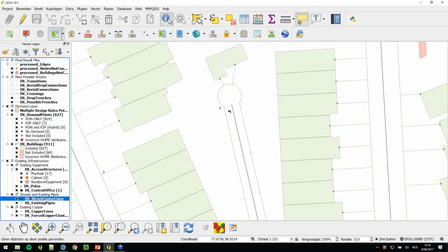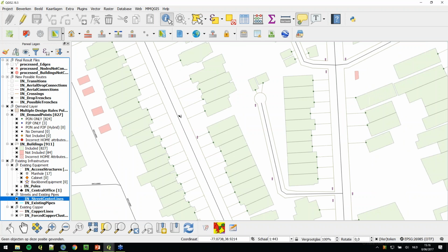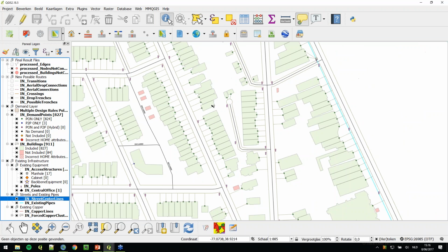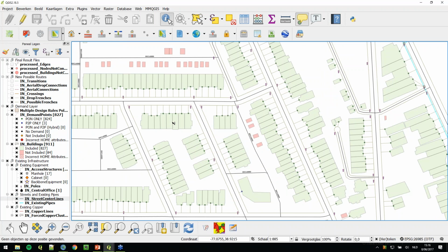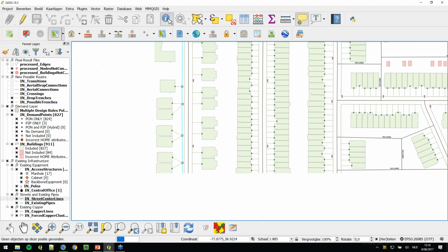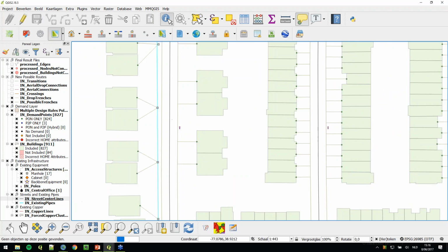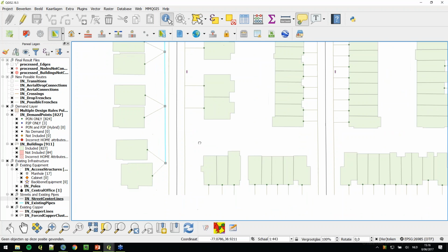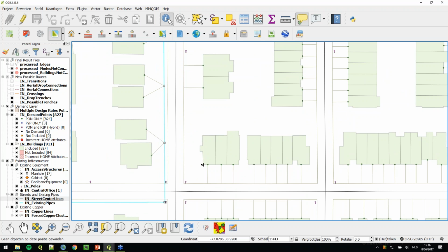Now, something that we changed related to the lead-ins in version 1.10 is a way to do priority lead-ins. So if I go here to an example, it's possible to set priorities for the lead-ins. What does it mean? You can choose to do the lead-in directly to the newly created possible trench, but you can also drop directly to maybe existing manholes or to existing pipes, and you can set a priority for this.